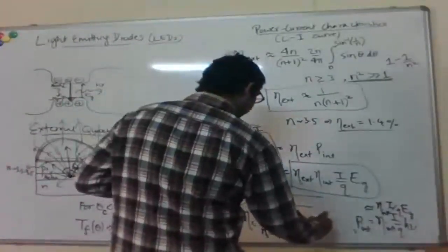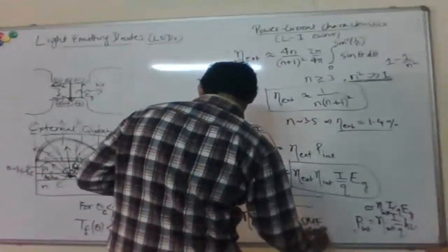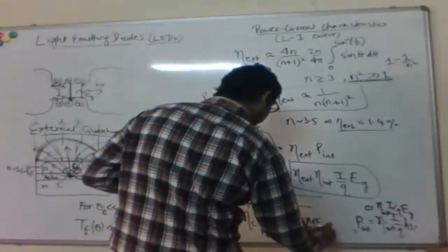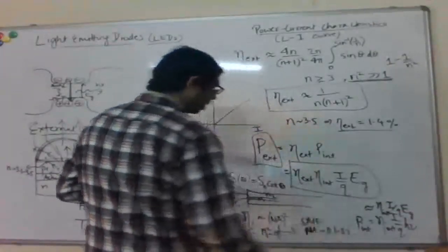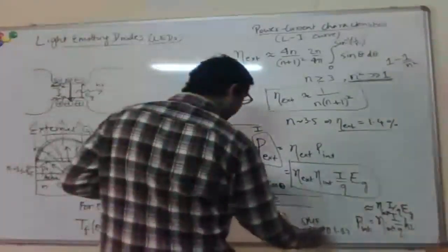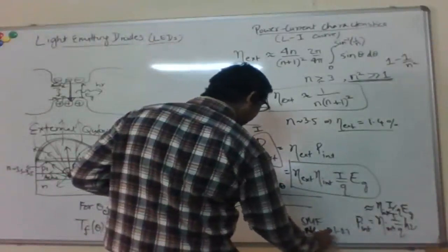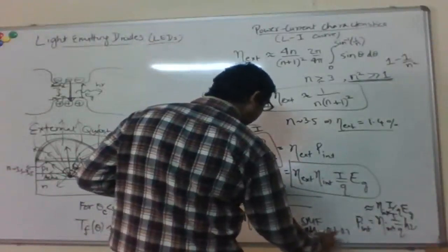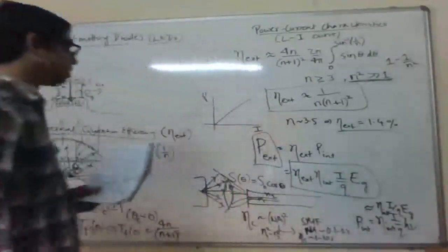So if you take a typical single mode fiber, the NA is quite small. Let's say between 0.1 to 0.3 or something. It's closer to 0.1 typically. Right, so the coupling efficiency is the square of this, right? So you can see that's only like 1% or so. So definitely less than 10%.